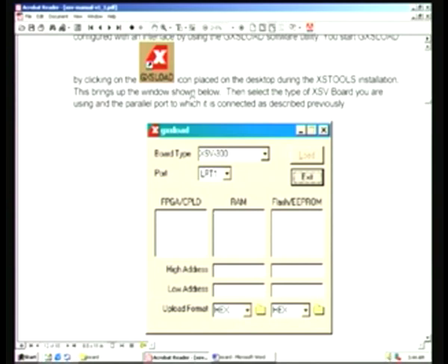we have to load the bit stream, which you have already developed during the last session, right up to the place and route. You have got a bit stream, and that is what you need to download in order to download your application code. Prior to doing this, you also have to initialize the CPLD, because that particular CPLD is for managing the whole configuration, and you can also put your codes and execute small codes there, while major codes will always be residing in the FPGA Virtex 2, and this particular menu is once again for board selection.